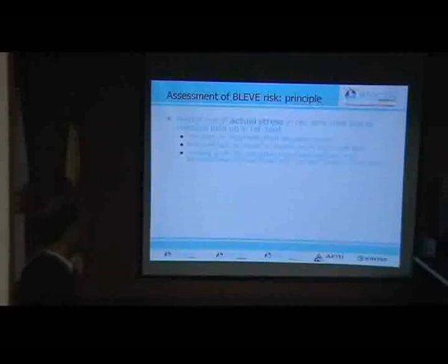So the principle of the assessment of the blast risk from the test results was to predict the actual stress in the reference tank, and then in the shell of the tank, due to the pressure build-up in the reference tank. It was shown from a simulation study that the end caps of the tanks were not important in this respect. The pressure build-up is caused by heating up of LPG inside the tank, and the heating up of the LPG is calculated from the measured tank shell temperatures with a simple lumped parameter model, and then the heat flux into the wet part of the test tank was directly measured and just corrected for the difference in area.